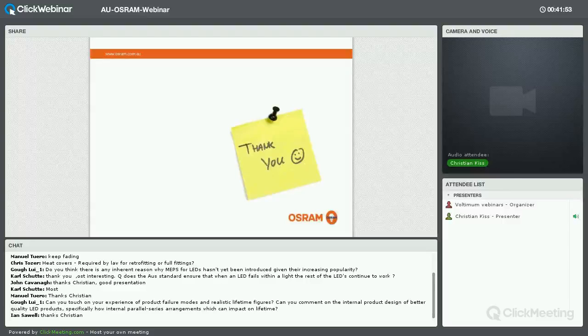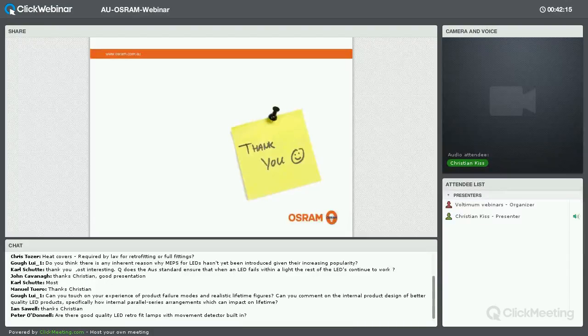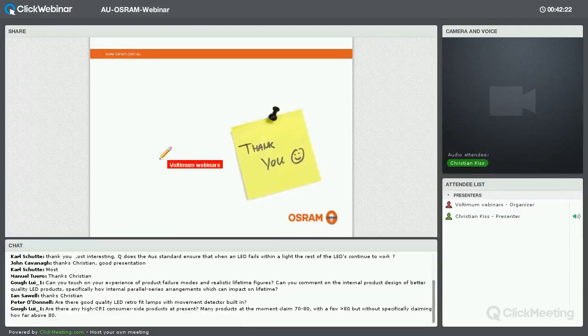Currently, to my knowledge, for retrofitting, say you had a halogen downlight, if it's a do not cover downlight, I don't believe you need to cover it, but you still need to maintain that 200 mil clearance around the downlight. But that's being reviewed now. There's a draft AS/NZS 3000 circulating, out for public comment, and I think some of these things will probably be more accurately addressed there. But to my knowledge, I think currently it's not mandatory.